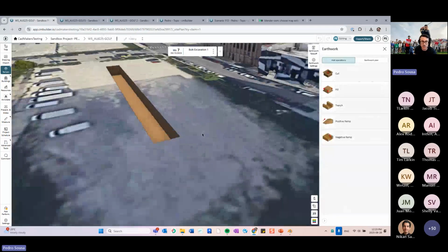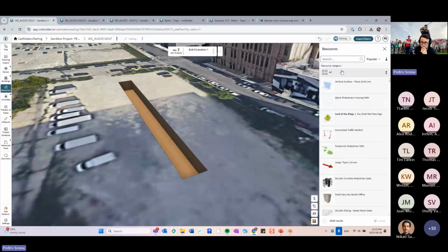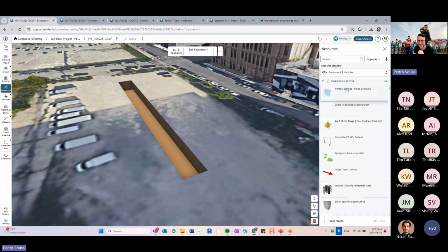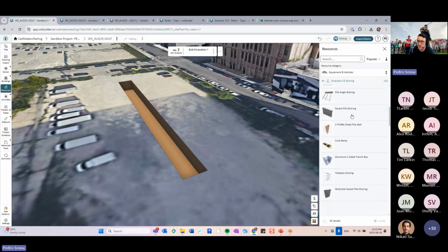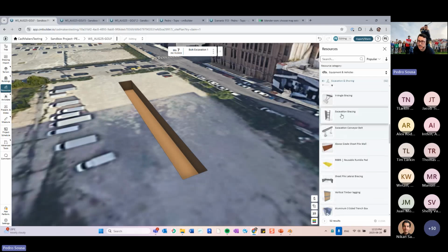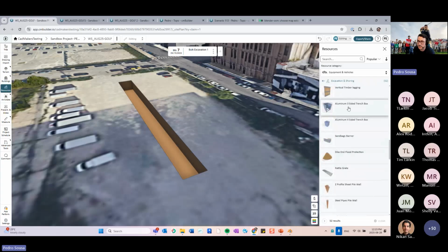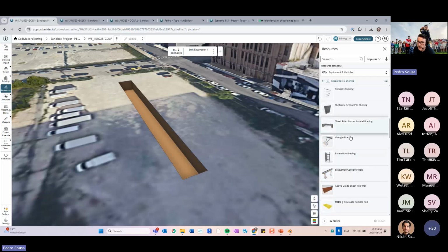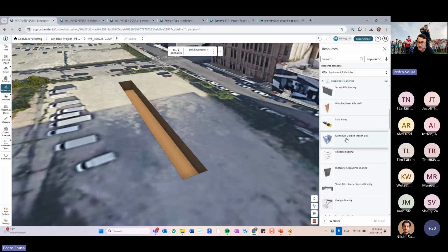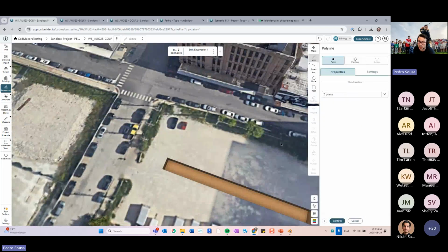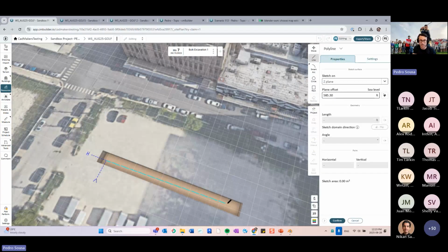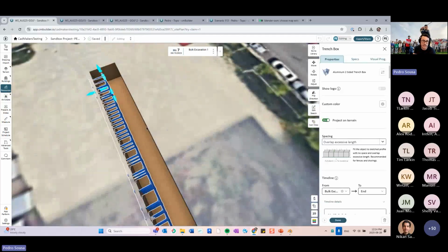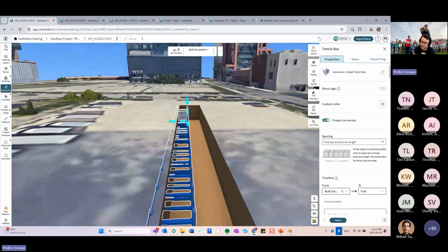You might need to use, for example, the trench shoring, the box. I forgot the name exactly. But if I go over here in excavation and shoring, you're going to find that we have this excavation bracing and some trench boxes that you can use. So this aluminum-sided trench box, I can put them as a polyline, and I'll just draw a line over here that will be similar to that trench. And when I hit confirm, I'm drawing a line quickly just so we can see first how the object behaves according to that line.